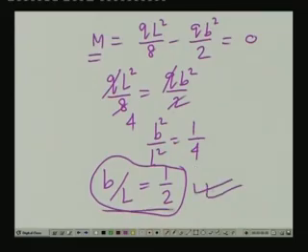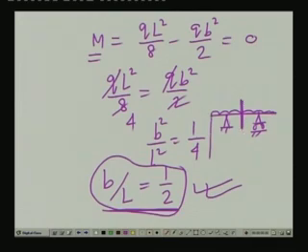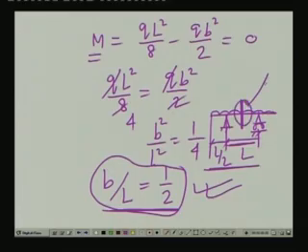If we maintain this particular ratio, then the beam which we have seen, where this is hinged and this is on roller with overhang of quantity B with uniformly distributed load, will produce a 0 bending moment over here. But then the value of this particular part has to be equal to half of this length. If this is L, this has to be L by 2. So, if you have this distribution, then the moment at this particular point will be equal to 0.